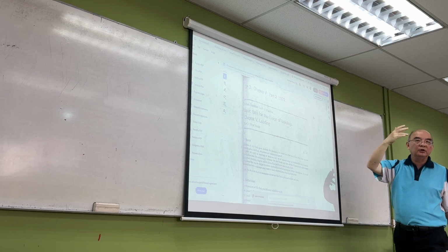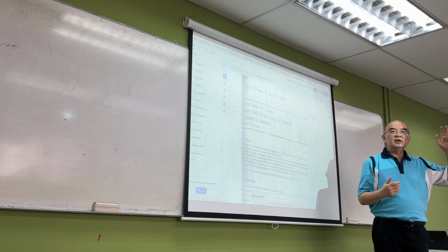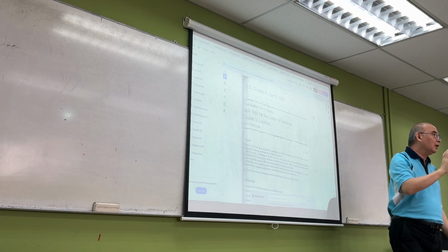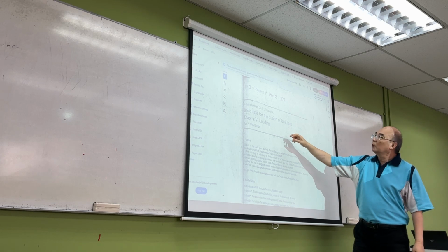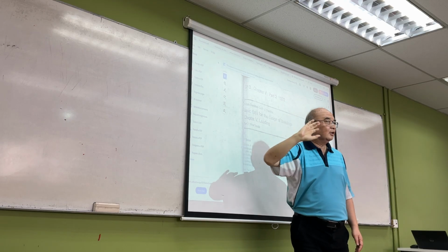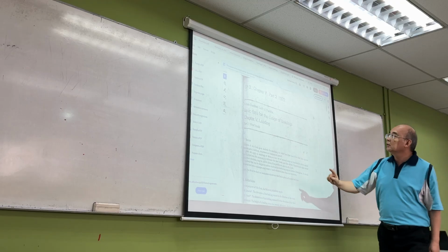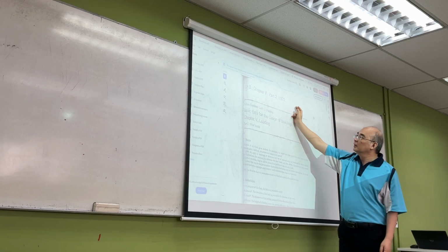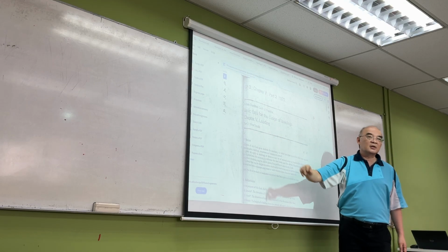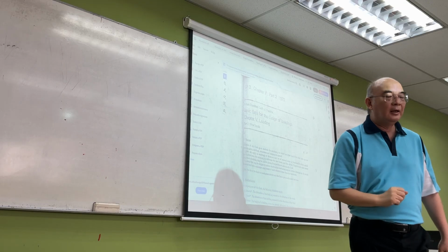the older generations, let's say people who are at least 10 to 15 years older than me, would use what they call CP3, Chapter 5. The older generation will talk about CP3. CP is code of practice, Chapter 5, Part 2, basic data for the design of buildings for wind loading. Then this is replaced by BS 6399 Part 2.